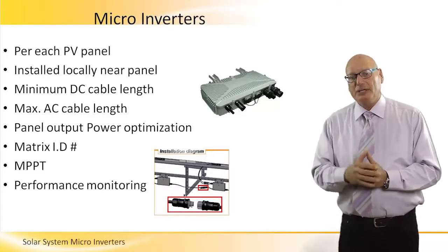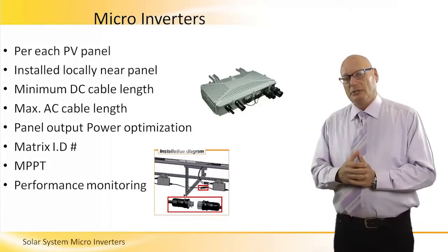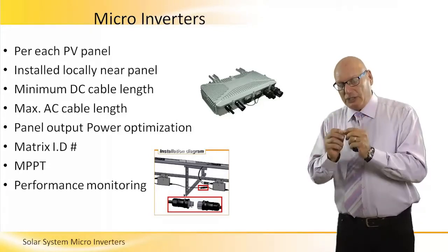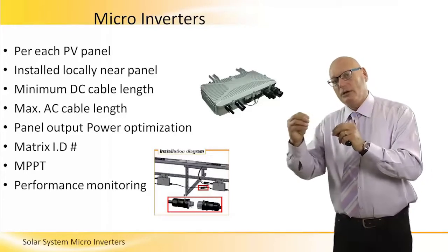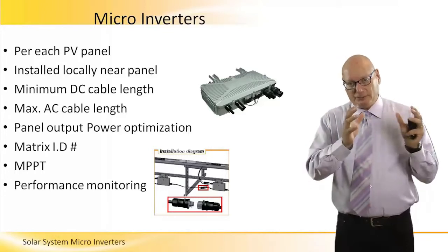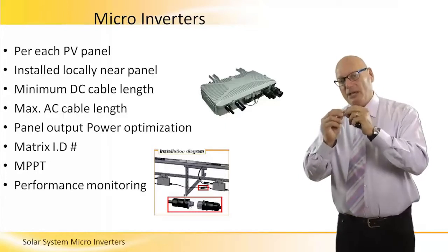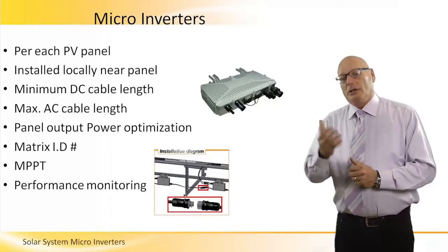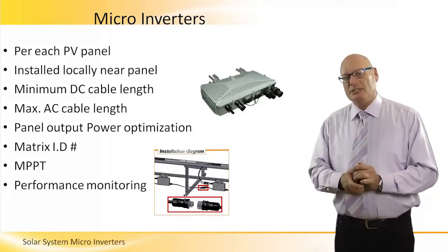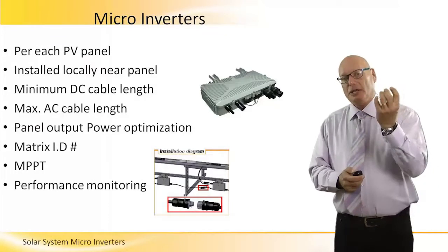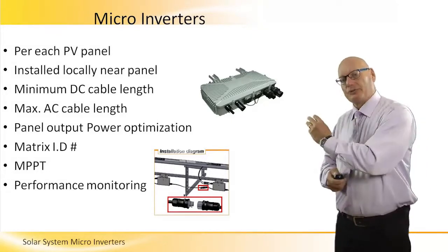Each microinverter has an MPPT, maximum power point tracker. In other words, it continuously calculates the maximum I times V, equals power, no matter if the specific panel is shaded or faulty or not, to keep the IV at its maximum. It also allows us to monitor the behavior of the system itself, because it senses the outputs coming from the panel, analyzes them, and reports.